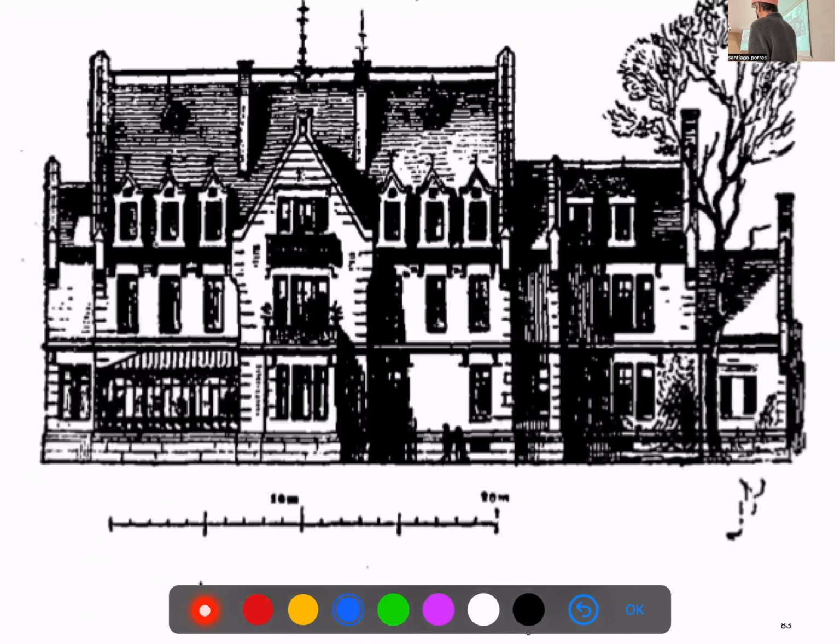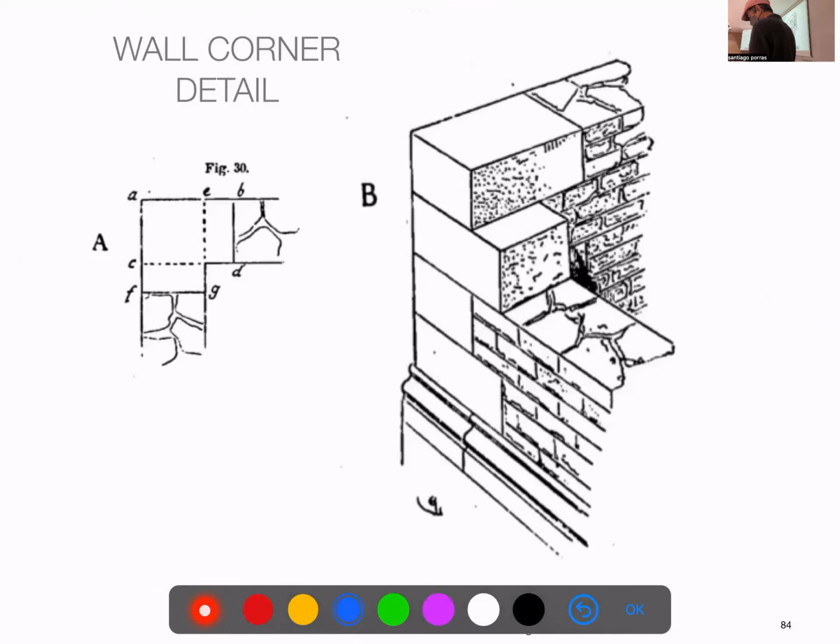And again, when you make a facade detail, a window detail, whatever, we need to have the context of the full facade, right? We always start from the full building. And this is, again, the modern building with the greenhouses, plenty of light and ventilation and so on. Again, the care for the corners. In all buildings, corners are difficult, not only in curtain walls. And this is why they have a special, more solid construction there.